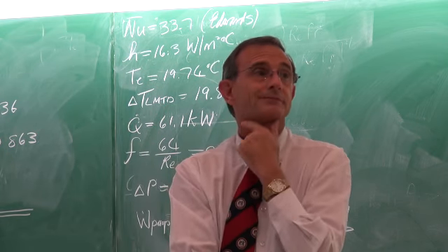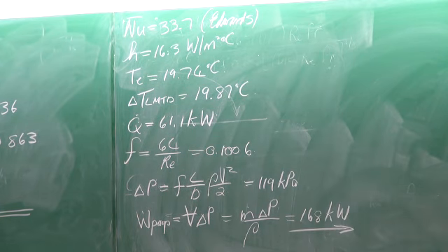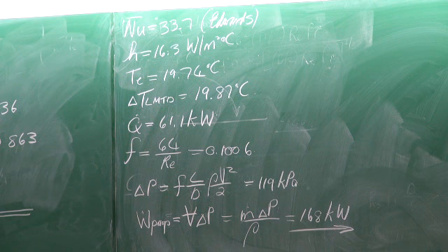Okay. Any more questions? Just with that Nusselt number there, when you say the average Nusselt number from the Edwards equation, does it include the fully developed region and the developing region? Yes, it is a very nice equation. So even if it's going in the fully developed region, it will do the calculation correctly for you. So if the fully developed length is very, very long, the equation will go to 3.66 in any case. Okay.